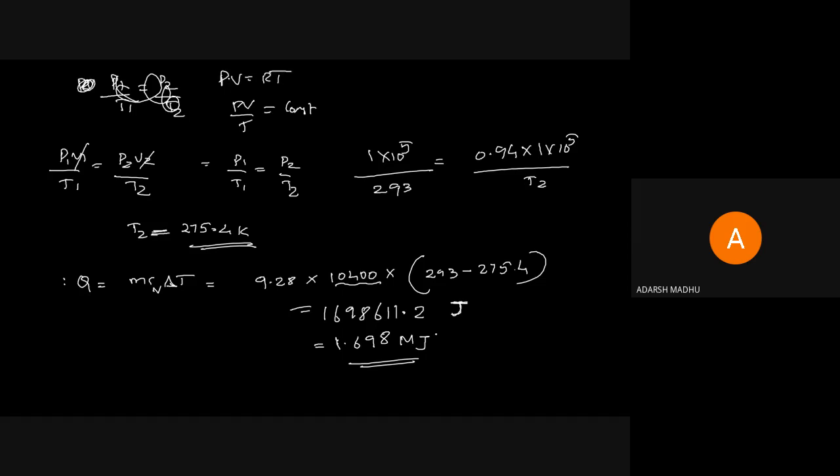That is a problem related to ideal gas. I will give you more problems, so do practice them. The equation is PV equal to m R T and R equal to R naught by M. And you want to know the molecular weight of some important substances: hydrogen, oxygen, carbon dioxide, ammonia NH3, like that. And for heat transfer, to find out, constant volume is m c_v delta T, constant pressure is m c_p delta T, as we had done in the question in the previous module. So that is for our session.